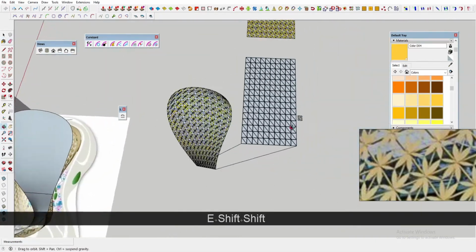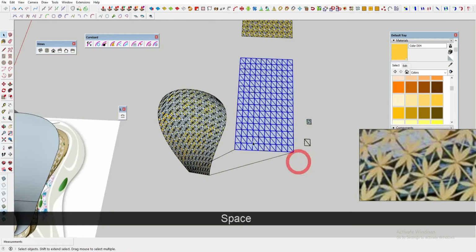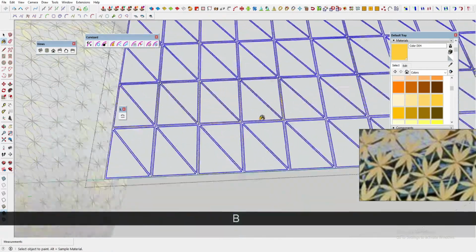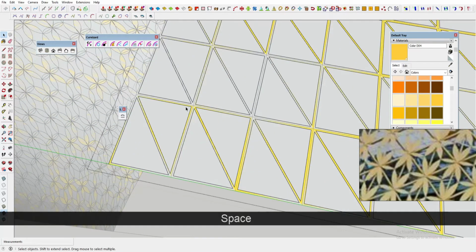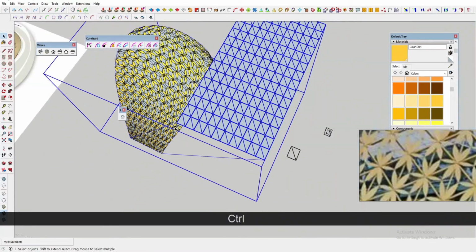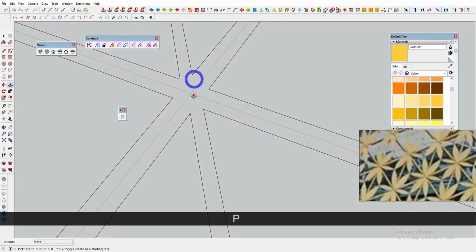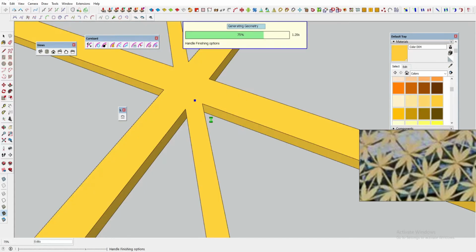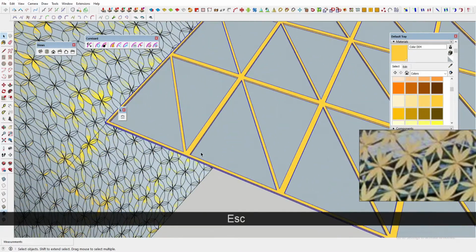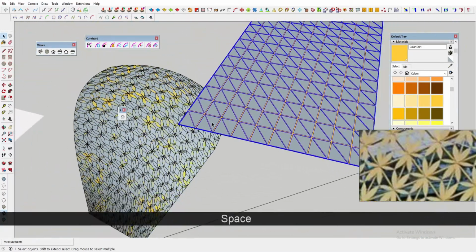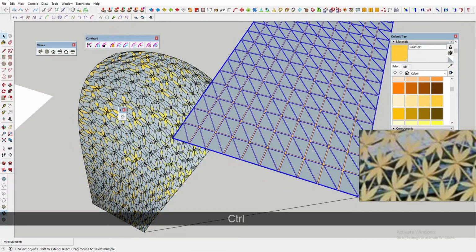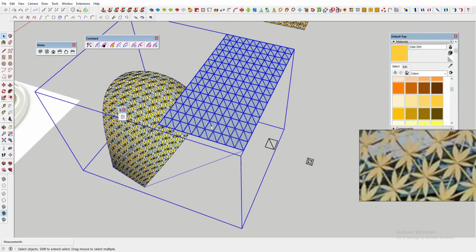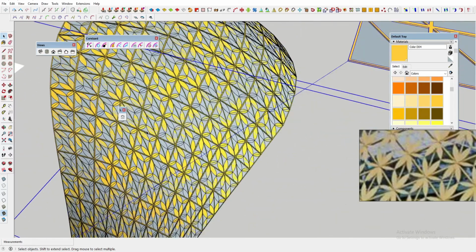Here I'm going to extrude the framework. You can see the framework below the pedal. I'm using the AMS smooth tool to delete these unnecessary edges. I'm using the Flowify plugin again. Here I extruded this surface with the joint push pull tool. I'm placing this whole group below the projection plane, because our pedal was made above the projection plane. As per the picture, the whole Flowify will be placed below the pedal.